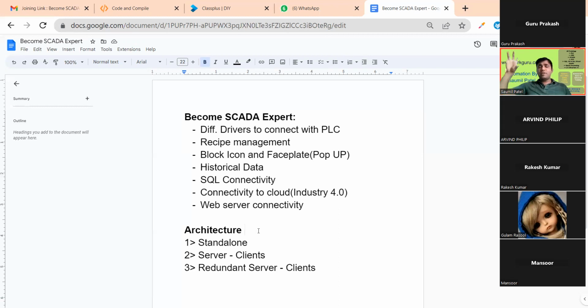What I can say is that you require 4 different IPCs in 4 different locations, right? And one is a control room. So you cannot have one control room SCADA and 4 different SCADAs to operate the process. Yes, it is possible, but it cannot be a good way to develop the architecture.